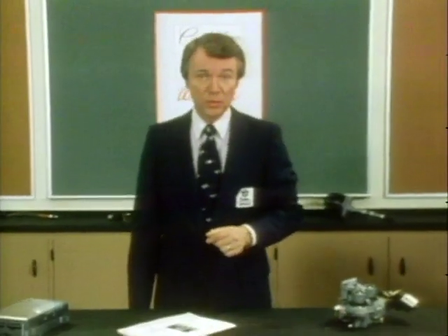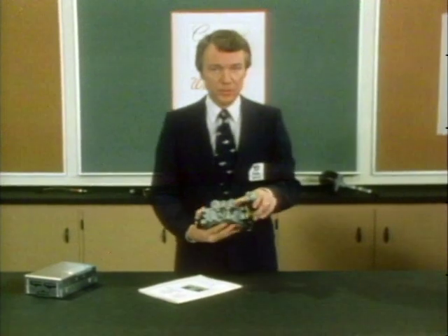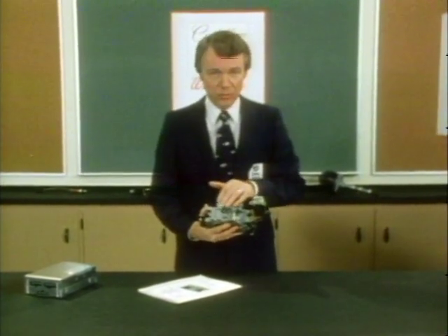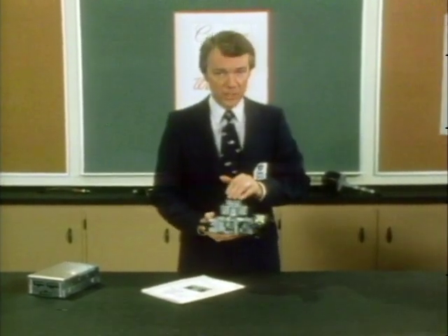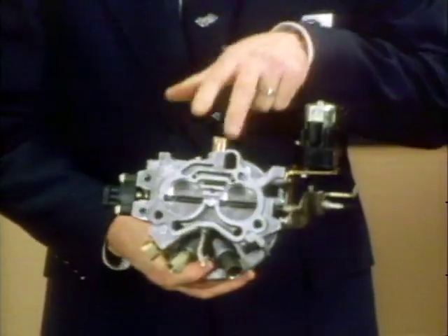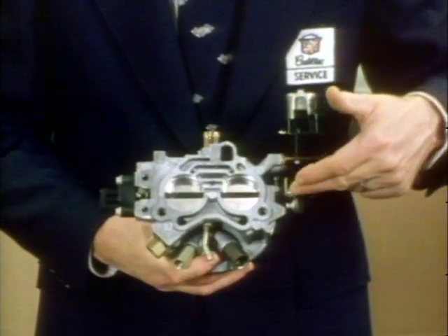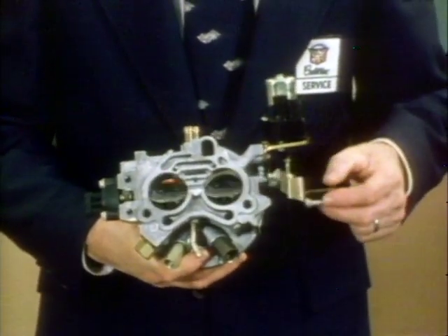The purpose of the next subsystem, the air induction system, is to control and distribute the air necessary for combustion to take place within the engine. The first of the 3 components that accomplish this purpose is the throttle body, which is located under the fuel metering assembly. The throttle body contains 2 bores, each of which has a throttle blade mounted to a common shaft, which is in turn connected to the accelerator pedal.